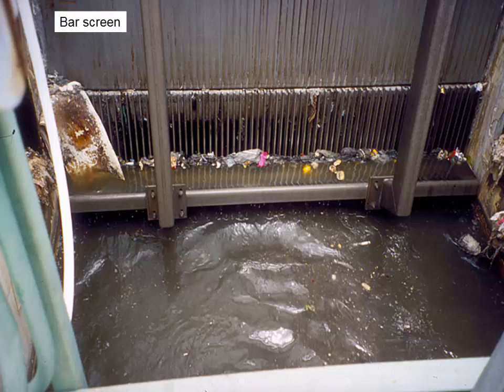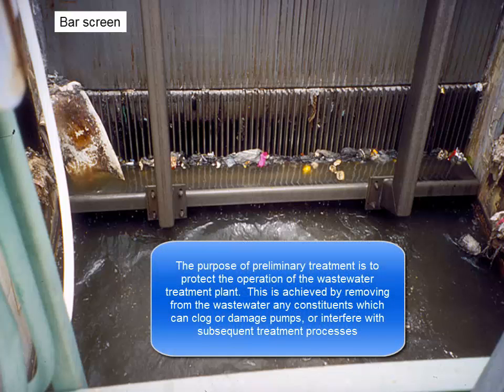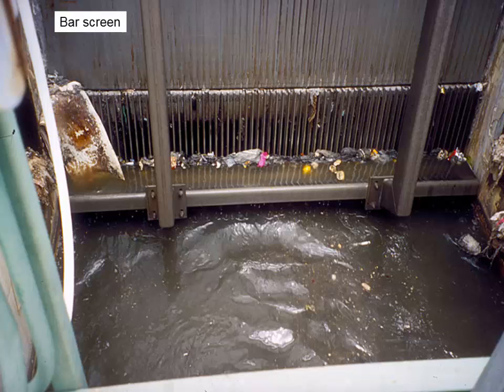This is preliminary treatment, physical treatment. Anything that goes down the drain, gets flushed down a toilet, or washes into a storm drain needs to be filtered out. Those things cannot go through treatment. So they'll get stuck at preliminary treatment on something called a bar screen. The water is passing through this bar screen, which will typically go down into the effluent.